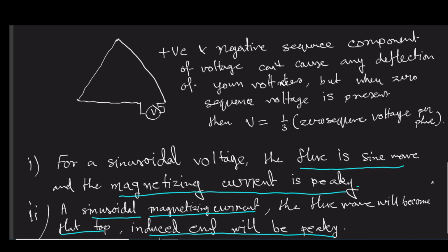Phase voltages are different than they should be in the case where only the positive sequence fundamental harmonics are present. You can have a particular value of phase voltage that is balanced, and time-phase-wise there is a difference of 120 degrees between each and every phase, but here it is totally different.